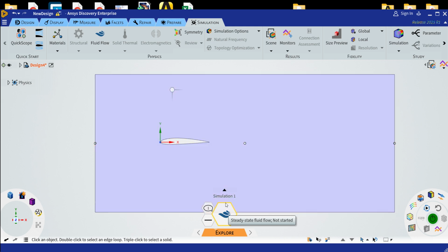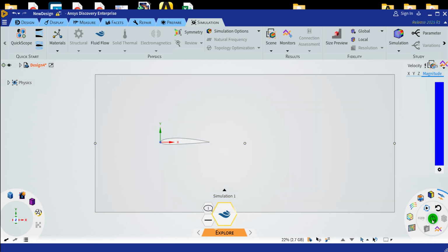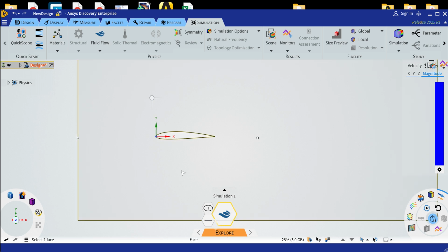will show you the progress. If the simulation is happening, there is a white color shadow which follows this ring, and this line shows steady or unsteady, that is, steady flow or time dependent flow. If you want to run, you can choose it. Now I'll go for a steady flow only. Now click on this solve button. Okay, it started solving.